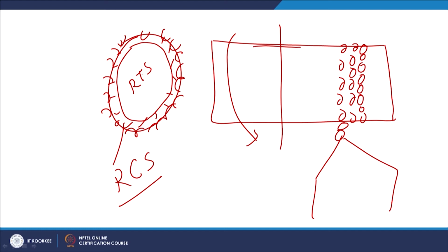If the residual stress distribution is seen, then the residual stresses are maximum at the surface and compressive in nature. Their magnitude keeps decreasing below the surface, then it becomes tensile, remains tensile up to a certain depth, and then again becomes compressive as it approaches the opposite surface.